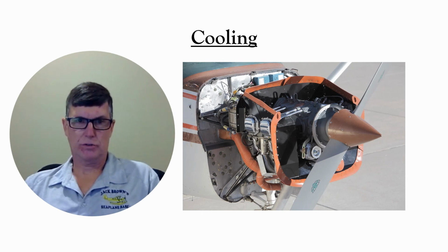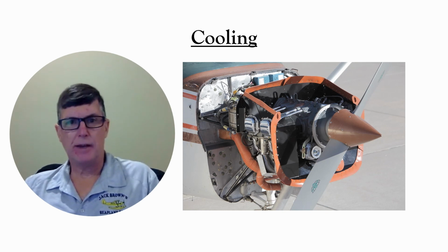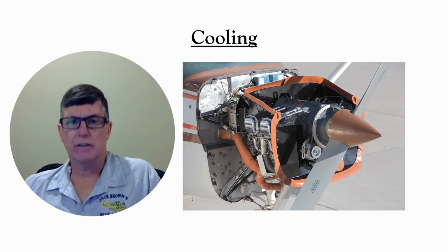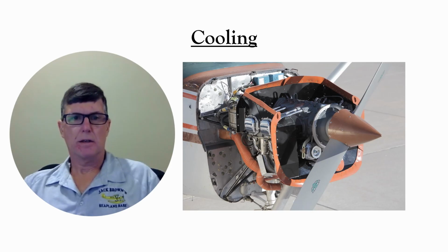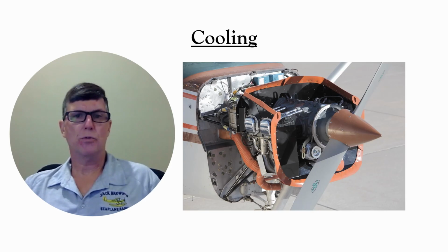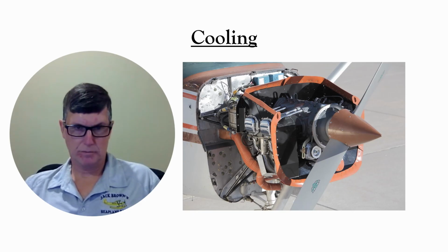A rich mixture increases the heat capacity of that exhaust gas. The extra fuel sort of acts as a heat sink for all that heat. The way the remaining heat gets dissipated is mainly through cooling fins around the cylinders.